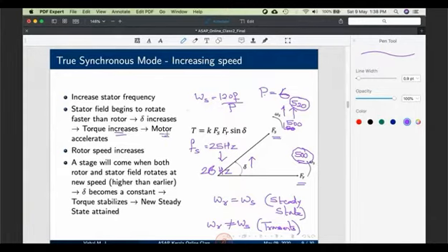Okay, so what you need after all, you just need an inverter which can vary the frequency. An inverter can easily vary the frequency using frequency modulation, as well as it can vary the voltage using pulse width modulation. So changing voltage or frequency or both is absolutely very easy for the inverter to do. Hope the concept is clear. And thus just by changing frequency, we are increasing or decreasing the speed of the synchronous motor. Okay.